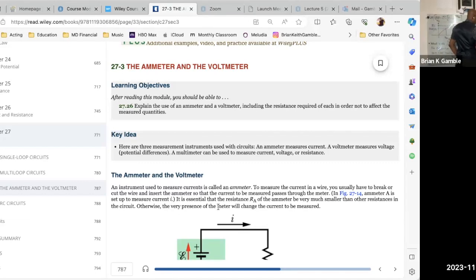So I open the circuit, I take the battery out, and then I close the circuit back up again with just the fully charged capacitor in it and the resistor. Well, what happens? What happens is that the capacitor acts like a battery. It discharges and the current goes around in the opposite direction. Basically all the energy then dissipates because there's no battery in the circuit to replenish the energy. The current just dies down exponentially and goes out to zero.